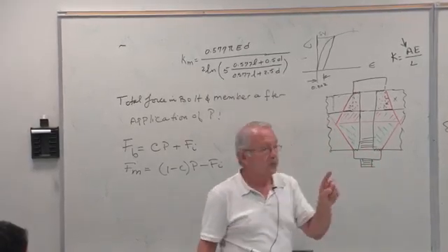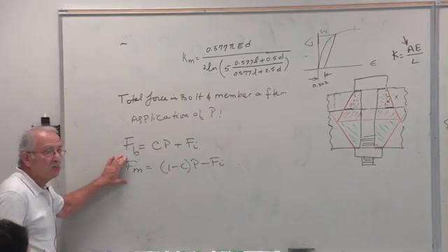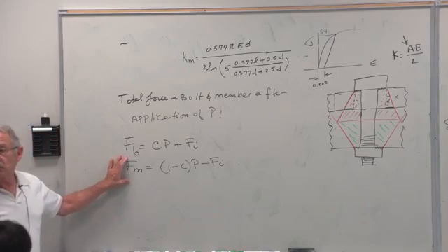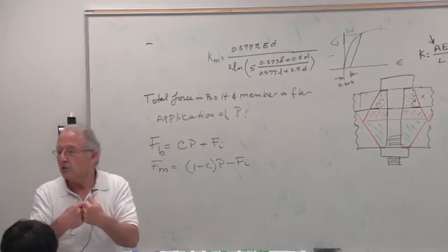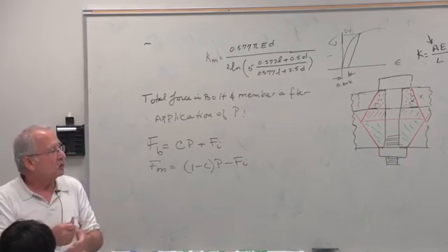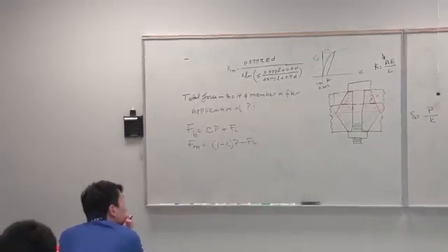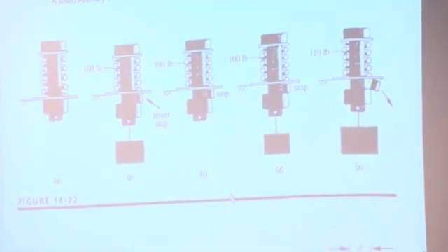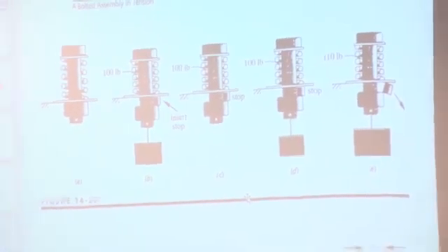The other is that the force in the member must never become equal to 0. There must always be a compression on the member. If you don't have any compression, you don't have a joint. All of the load will be carried by the bolt. So these are the two things we need to check for. So one by one, let's take a look.